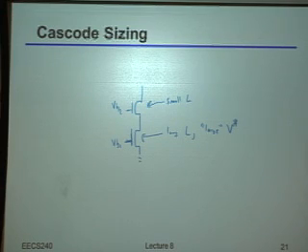Yeah, parasitic capacitance, right? Because if I make that a short channel, that will reduce the parasitic capacitance sitting there. So this is actually a very common and nice trick to make it so that you can not only get high output impedance at DC, but you can also reduce the AC output impedance, at least up to a certain frequency. Because by making this a short channel length device, I can reduce its drain capacitance, which, if I've done things right, is the dominant loading on the final output. So indeed, you will tend to make that a short channel length.